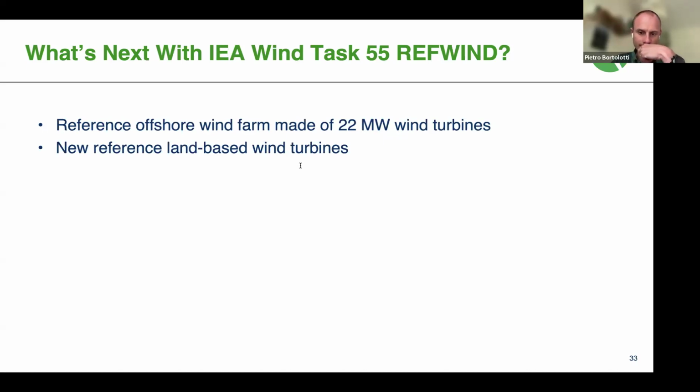Oh, definitely. Yeah. So the dynamic stall models have been giving us a lot of headaches, at least me in OpenFAST. Right now the OpenFAST model on the repository has all the different options, the different implementations of the Beddoes-Leishman model, so I would start from that selection and expand from there. But the answer is yes, absolutely.